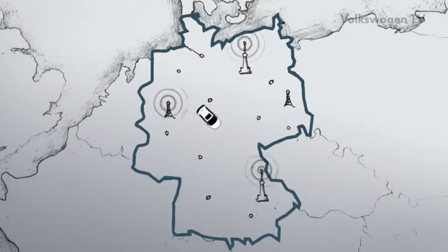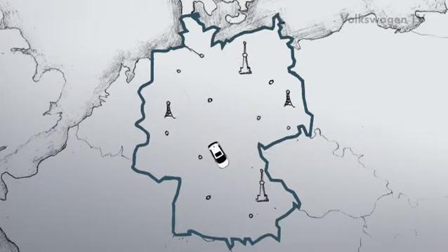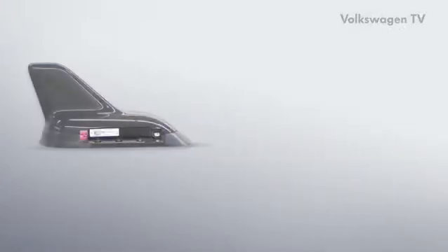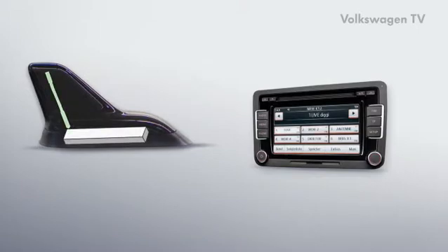As a receiver, the vehicle continuously changes its position with regard to the transmitter. The received signal is thus subject to variations in strength. The aerial amplifier compensates for these fluctuations. The amplifier is located between the aerial and the radio. It is also called the impedance transformer.